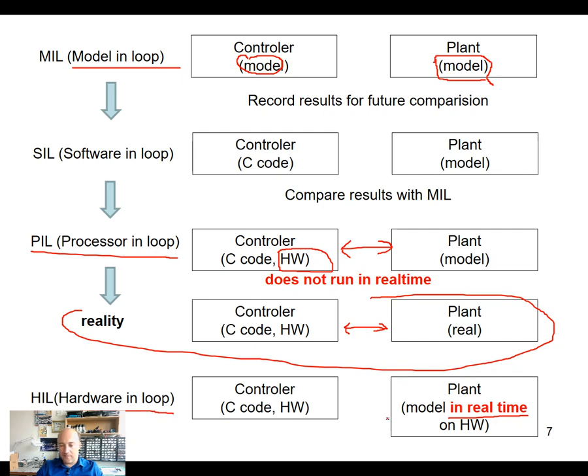So every 5 minutes you read the temperature, you do some control algorithm. So here this will be your temperature, this will be the measured variable y. The controller will calculate what it should do, if it should turn on the heater or turn on the cooler, and then it will send the output signal to the plant.